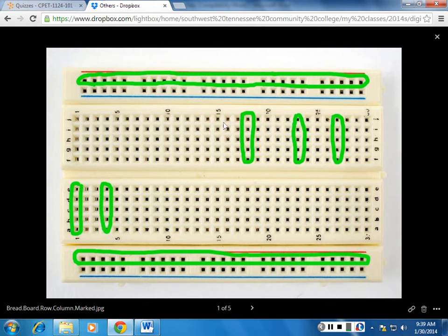Okay. Now, if you have only one single rail at the bottom, you are still fine. You may not have two. In some cases, some breadboards just have one here. So it's only one. So mostly you use the top one. If you have two here, you can use either one. You can use the top one probably as a VCC and choose anyone from here. But remember, if you are connecting to this hole, that means the top row is connected, not the second one, because the second one is again separated. It's a single row.